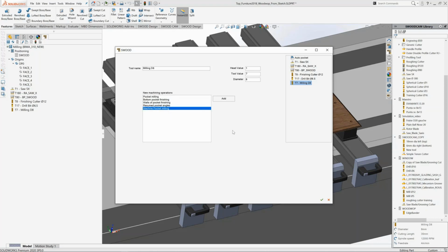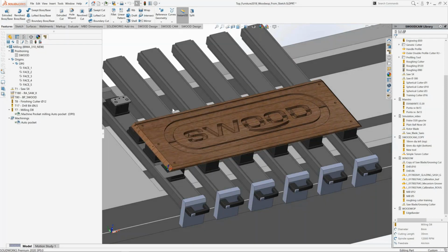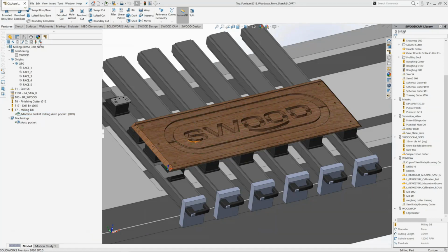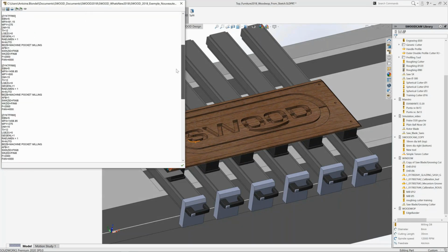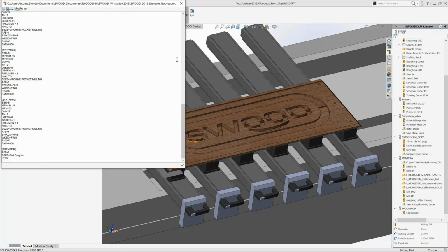One of the very important things is to have the possibility to communicate with the machine interface on the different brands like HOMAG, Biesse, SCM, and so on. So this year we had the possibility to create new pocket definitions and directly generate in our post-processor and in the code the language to communicate with our pockets, with the pocket macro defined in the software of your machine.